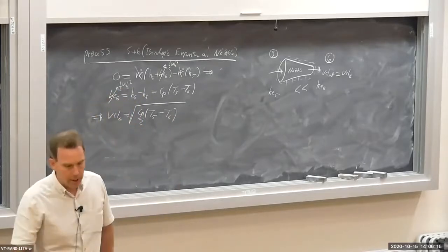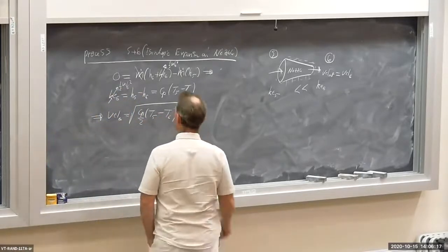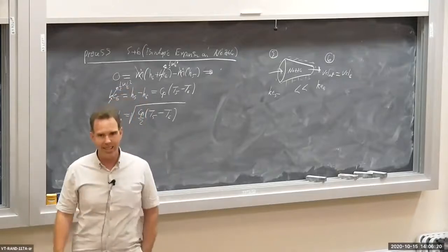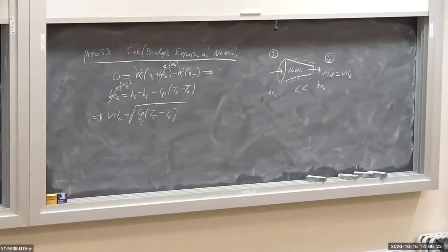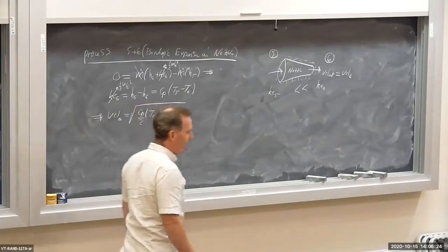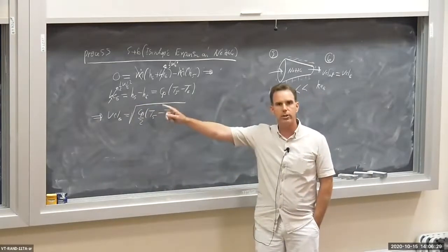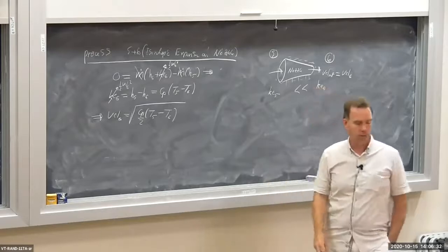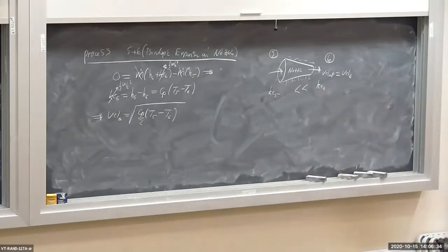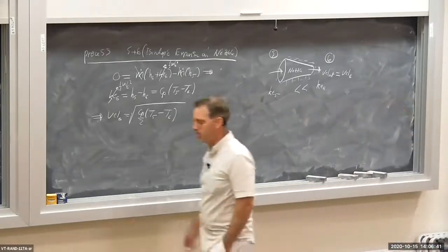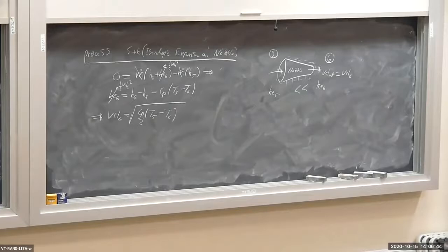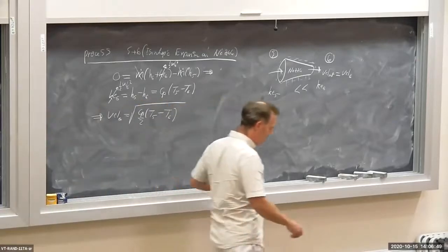Okay? Now, one little thing to be careful of here, we'll show this in a minute. The CP has units of kilojoule per kilogram degree Kelvin, whereas I want it to have units of joules per kilogram degree Kelvin to get velocity here instead of velocity with some weird unit. Velocity in meters per second, not square root of kilometers per second or such, okay? Okay, so I clearly have to get some quantities here. I have to get T5 and T6.